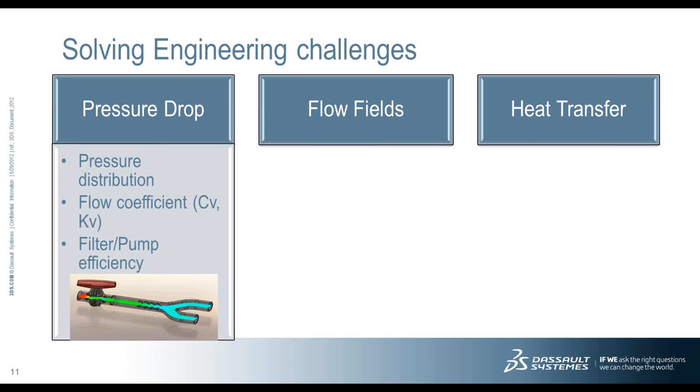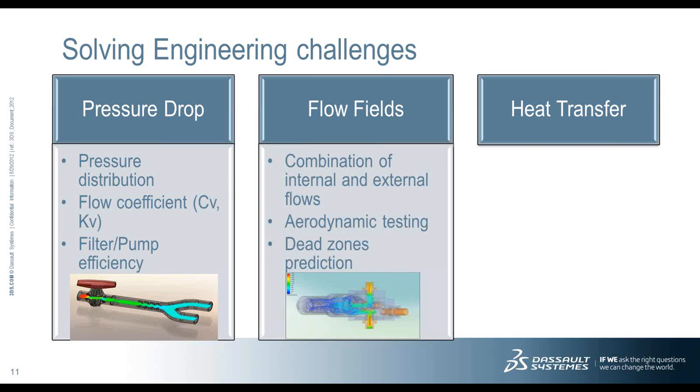For example, the objective of a duct design is to size the ducts so as to minimize the pressure drop through the duct while keeping the size, and then the cost, of the ductwork to a minimum. SolidWorks Flow Simulation helps designers to investigate and optimize pressure distribution in a wide variety of products such as valves, nozzles, and control devices.